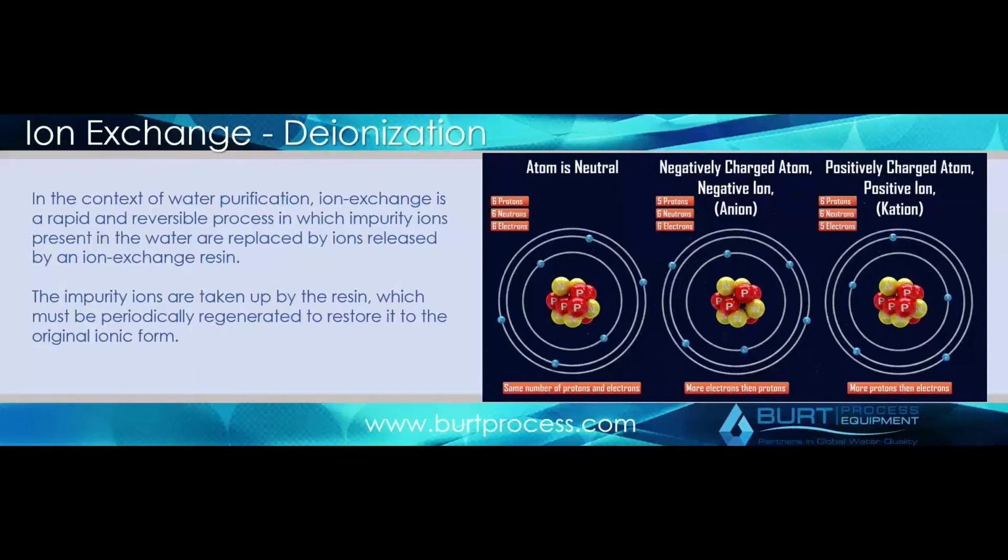The problem with chemical ion exchange is you only have X amount of sites in the system. So as you operate an ion exchange system, you have what's called resin exhaustion. With resin exhaustion, you'll then have to regenerate the resin, so you do have a bit of a consumable here. It's one of the reasons why people would want to put an RO upstream of any kind of DI bed. In a lot of cases, if you just brought basic city water to a DI bed, you would exhaust the resin very quickly. It could be a matter of even a couple of weeks.